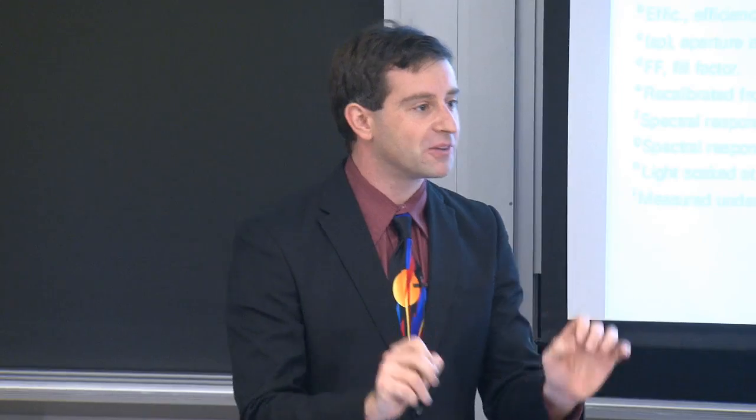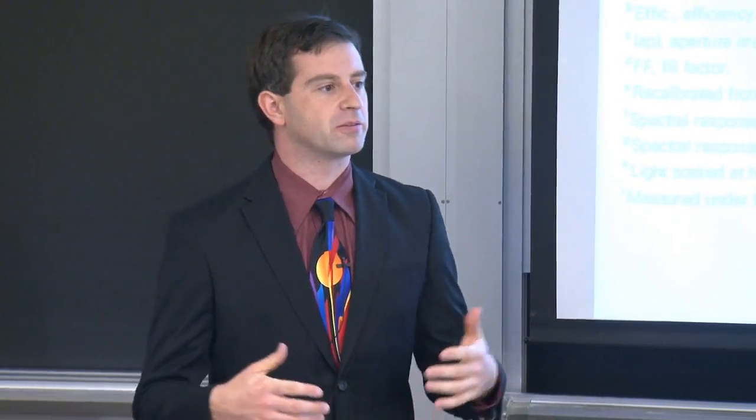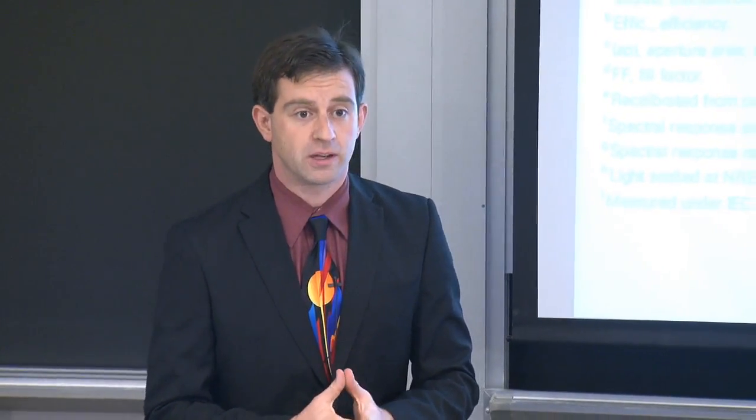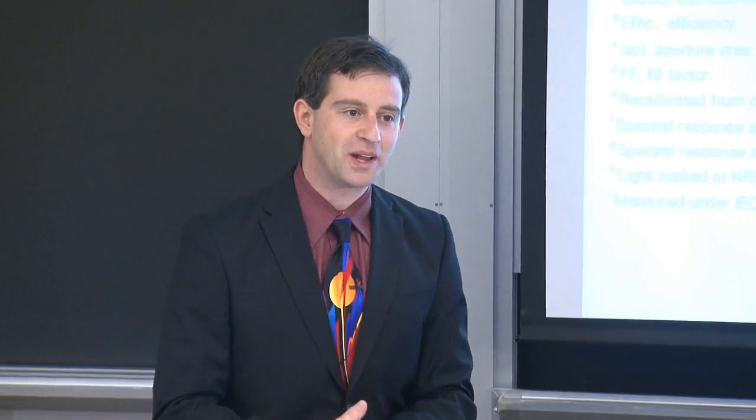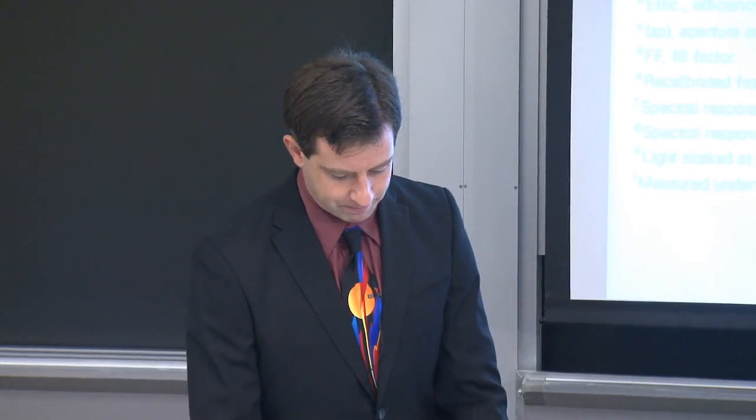In other words, in that large specimen, there was one point that was extremely weak, another point that was sort of weak, and another point that was mildly weak, right? And as you increase the size of your specimen, the likelihood of having one of these failure points increases. That's an analogy, let's say, to a large area module as well, that we could have pinholes or other manufacturing defects inside of a large area module that could reduce the performance locally, and because everything is interconnected, it tends to drop the performance overall.